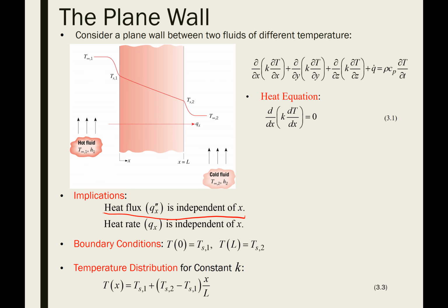So if you had a material where the thermal conductivity was not constant, instead of just dividing through by k, we wouldn't be able to do that. You'd keep k in there, you'd plug in the functional form of k, and then you would just do the integration with that functional form of k. I'm giving you some strong hints on your first homework problem for next time. It's that same basic approach, but with one little twist, to see if you can go through this whole process on your own.